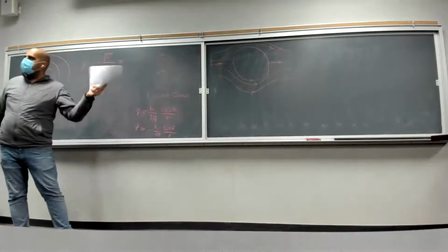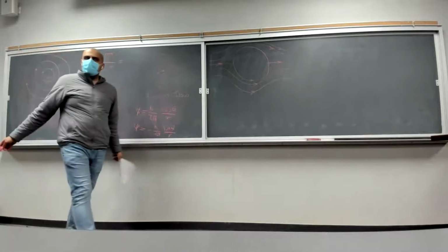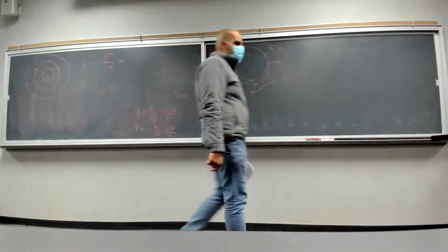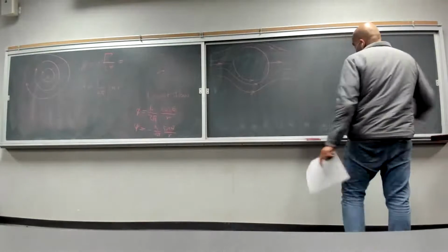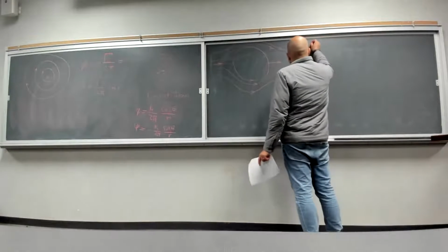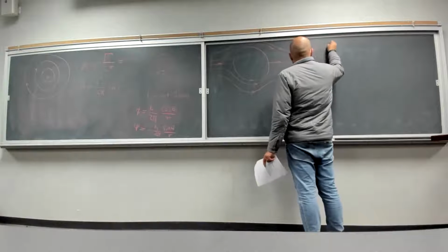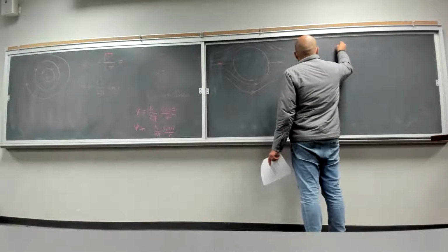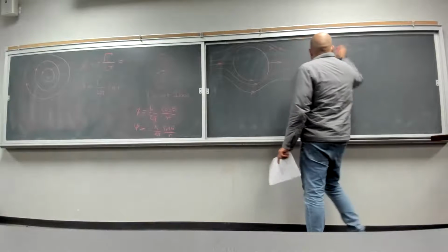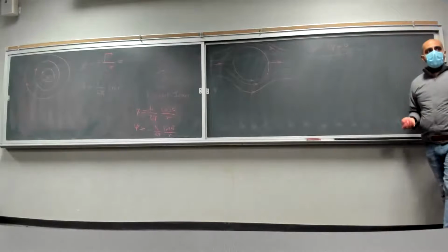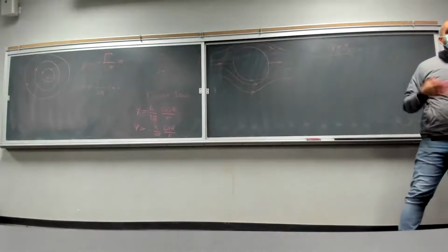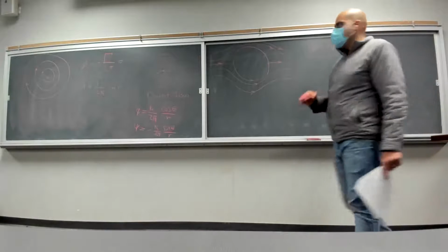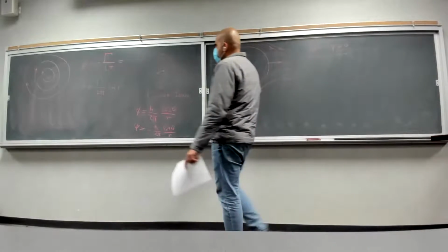This is an inviscid incompressible irrotational flow, all of those things, which essentially means that for this type of flow, the Laplacian of your velocity potential and Laplacian of stream function is 0. What does it mean? It essentially means that we can use simpler flows to build this more complex flow.